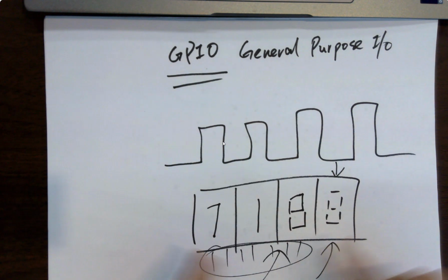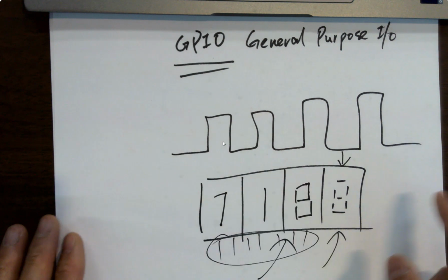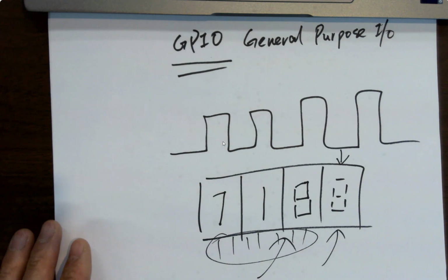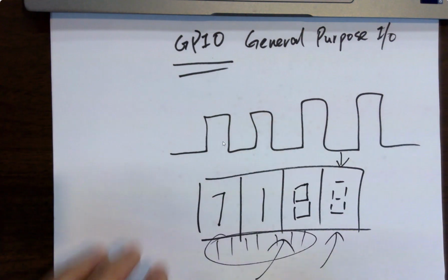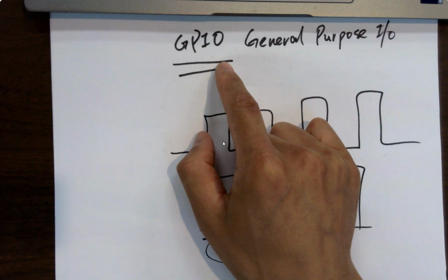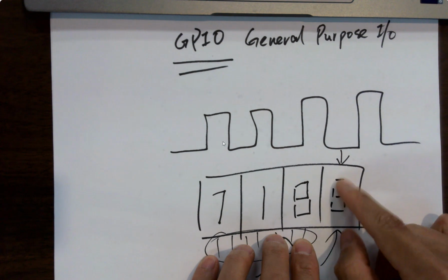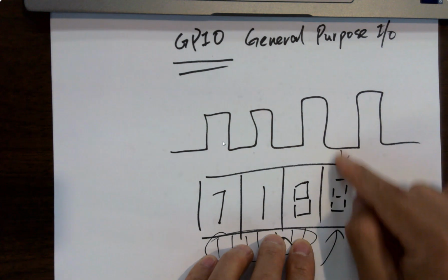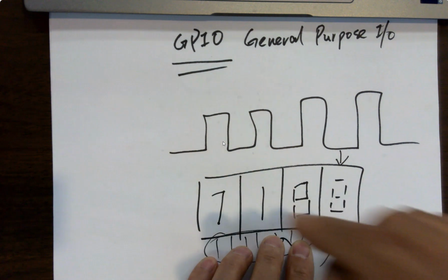Since you can do it super quickly, it looks like it's static, but actually it's not. So why do you want to use a microcontroller to do it? Since your microcontroller can run it and scan it super fast, you can run it at a microsecond or millisecond level. And these are all controlled by the GPIO pins. You are throwing digital numbers to the pins, which are controlling the single LEDs on and off, and also the scanning pins as well. So that's why you want to use microcontrollers, because they can run super fast.